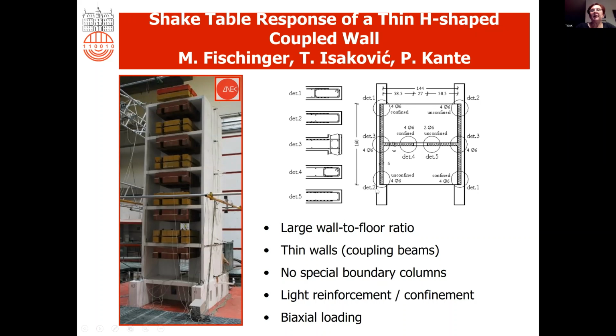In the boundary elements, we used different kinds of transverse reinforcement, one according to Eurocode, one according to the older practice in Slovenia. And we actually expected flexural behavior and failure of these walls.